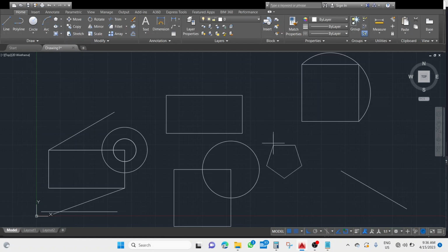So after that you have to give the orientation, and let's see, I want to draw the pentagon in this direction, then just simply type the length of the edge. So I want to draw the pentagon of side 50 mm in this direction. So here I have given the orientation, just type 50 and press enter. Now here the pentagon of side 50 is drawn.